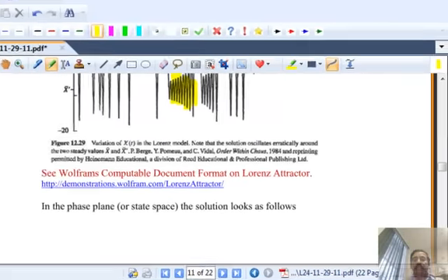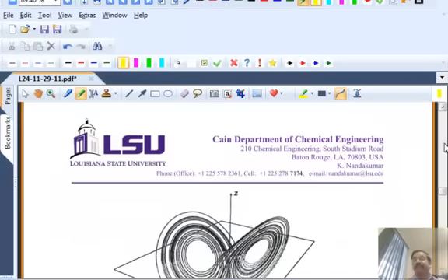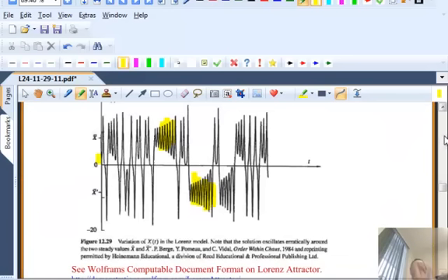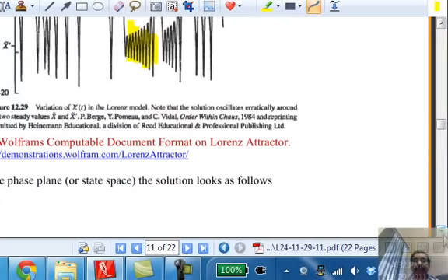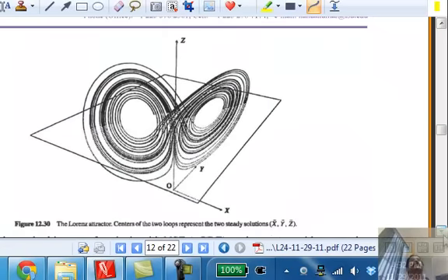And turbulence, if you look at the turbulent velocity profile, it will have signatures exactly like this. If I measure the velocity at a particular point, it will look completely random, describable only by statistical means. So statistics is a big tool that has been used in looking at turbulent flows. Any questions? So that is the state space projection of XYZ in the so-called strange attractor.